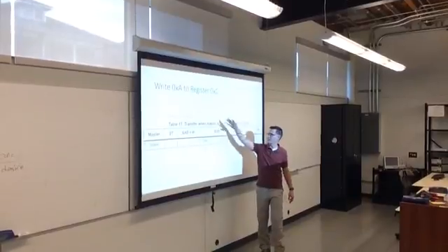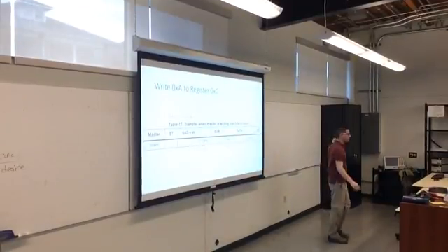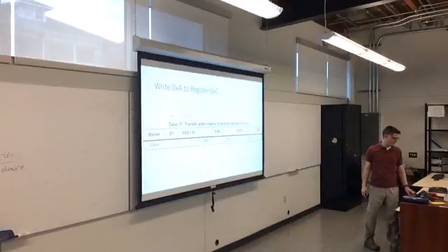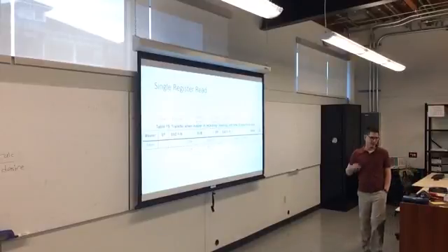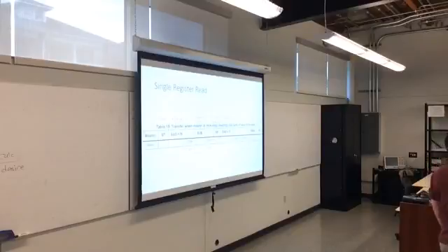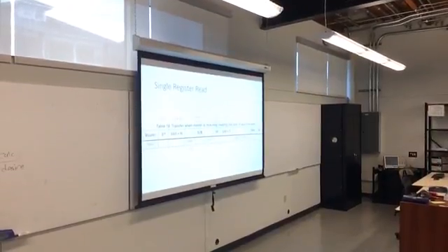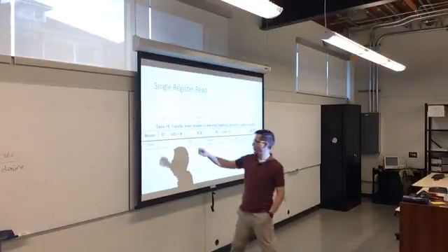Same thing with a read. Now the funny thing about a read is that you basically write the address to the device and then you start a new transaction that's a read. So you do one transaction that says, hey, here's some data I'm giving to you. And then once you write that data, you then have to read it back. So you start, you do a write transaction to the device, and you give it the address that you want to eventually read from. They will acknowledge, and then you start a new transaction.